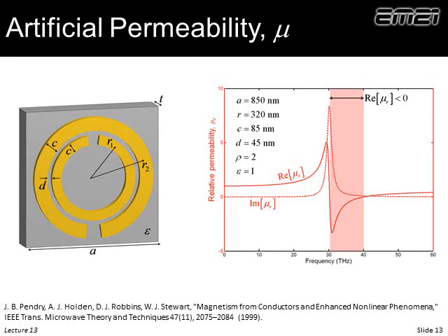The very famous split ring resonator. We see rings, so we can already envision this has circulating currents. This will be storing its energy primarily as a magnetic field. So we would say this has a magnetic resonance. And just like before, where we had an electric resonance, if you will, that gave us a permittivity. Here we have a magnetic resonance that gives rise to a permeability. And again, its response looks very Lorentz-like. And so there's this analogy between what gives ordinary materials their properties and what gives metamaterials their properties.